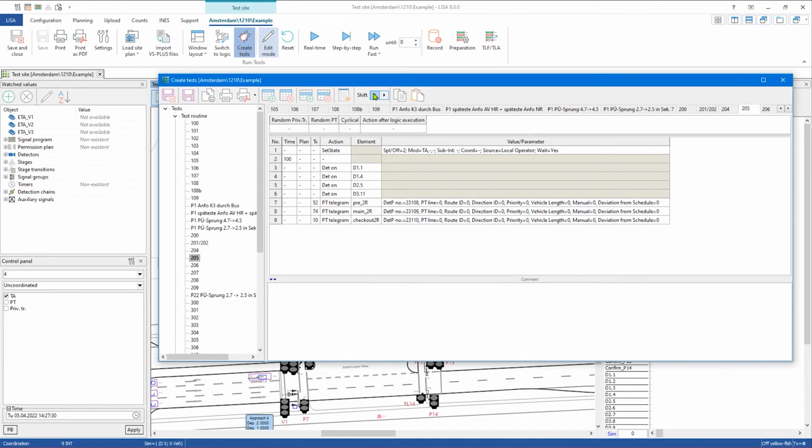You see also that LISA keeps in mind there is a maximum cycle duration. So this is a cycle time plan with a cycle duration of 75 seconds. So you can now shift. If I exaggerate this value, you see that it goes to 0 and starts here again. And I can also shift it back. So that's possible now for these lines.